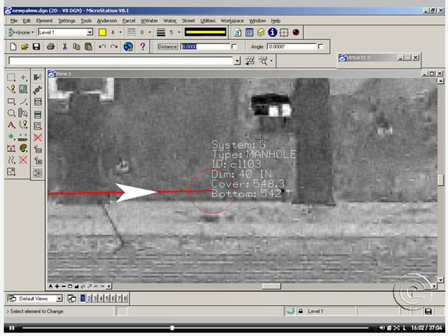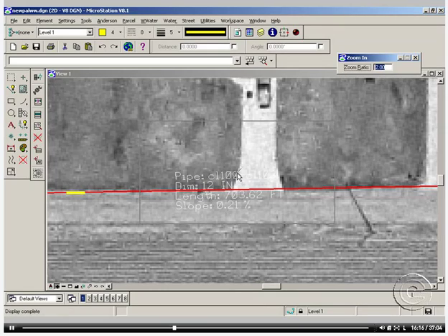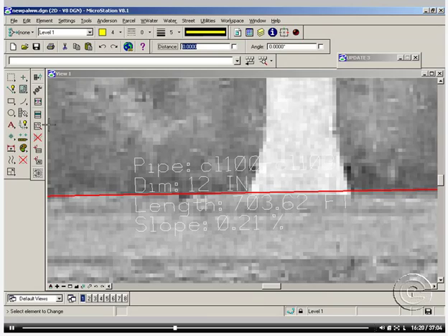And as you can see, the system that was R before is now S, which corresponds to wastewater, and the ID number of that node that was CL102 is now CL103. And not only is that node changed, but everything else that is linked to that node is also changed. As you would see here, your pipe that was before CL100, CL102 is now CL100, CL103.